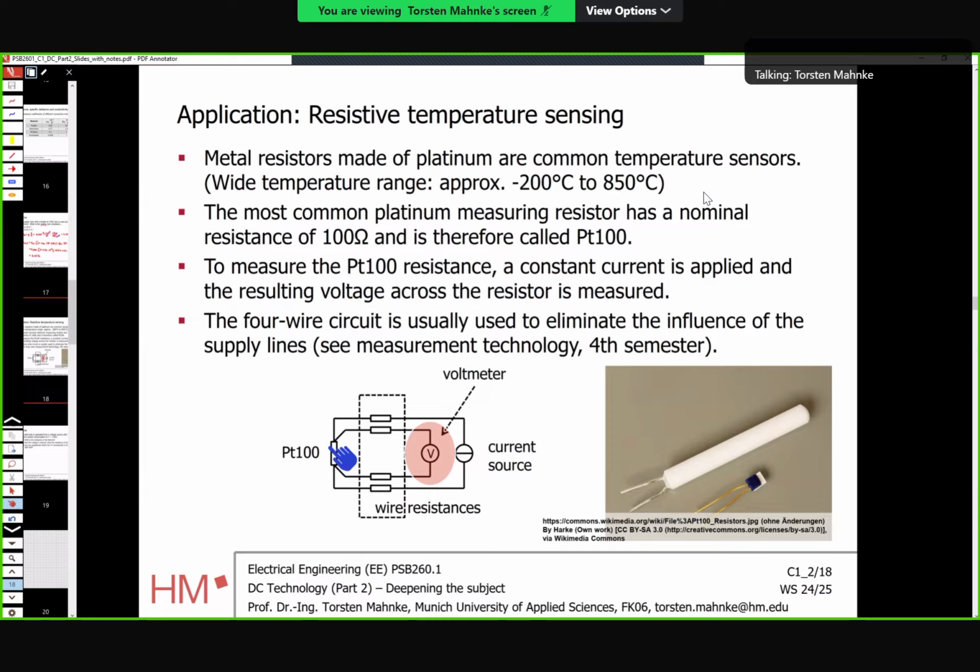Very often in laboratories, when you test electrical systems or anything else, you test them under elevated temperatures, hot or even cold. You use a climate chamber for that. You put the system into the climate chamber, and there's a little opening on the side. You can feed wires through that opening into the interior of the chamber, and among others, you can use a PT100 and bring it into the chamber.